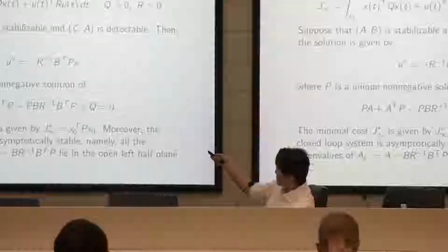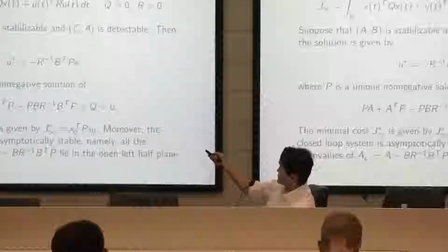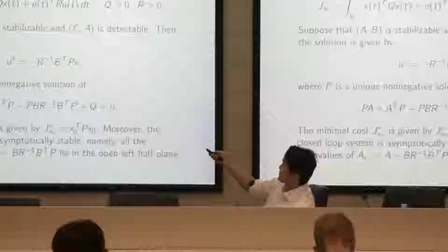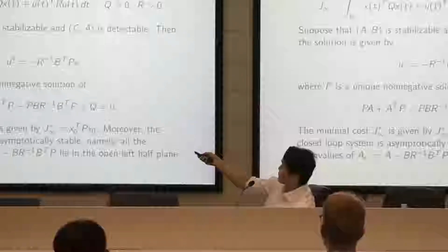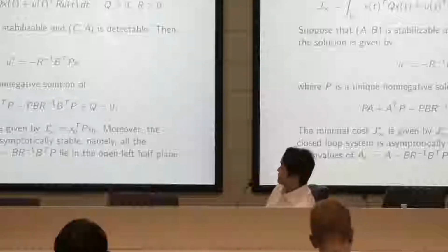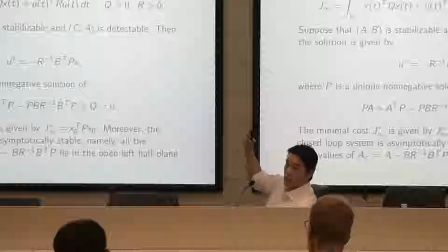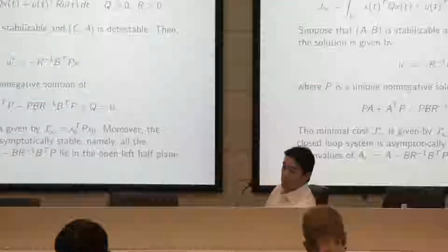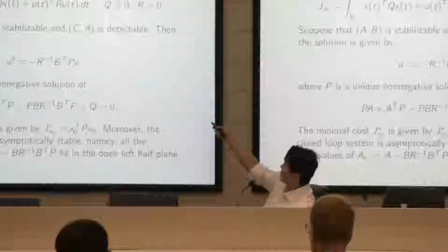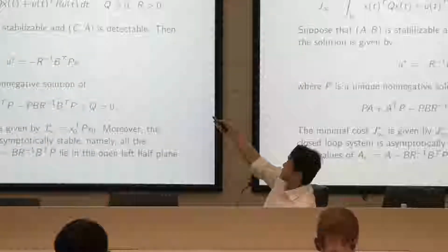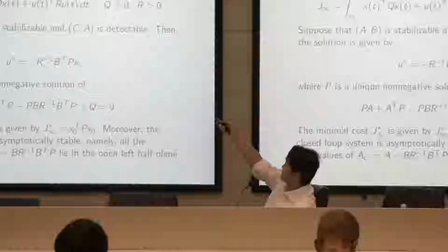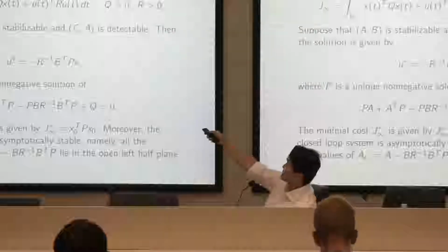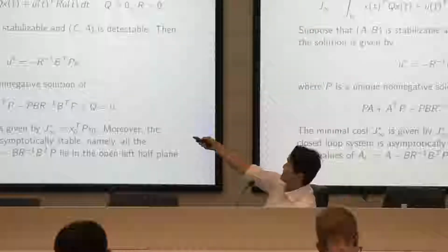Input is the feedback, because this is just a constant matrix. And x is the state. So the state is fed back and plugged into this u. And the overall system, which we often call the closed loop system, is autonomous. For any initial value x naught, the behavior of the closed loop system goes to 0 because we stabilize the system.